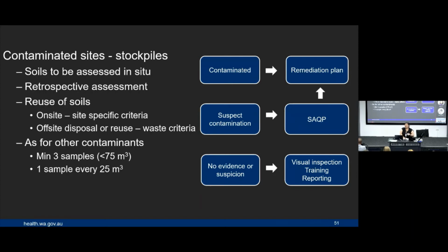If your suspect contamination is bonded and mixed friable with soil, then you're probably looking at AF samples as part of your sampling plan. So again, it's what are your data gaps that you need to address that should develop your sampling plan. So do I need to sample my stockpile for ACM only or ACM and AF? That's a decision you need to make based on the site-specific information that you have.